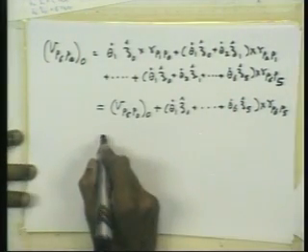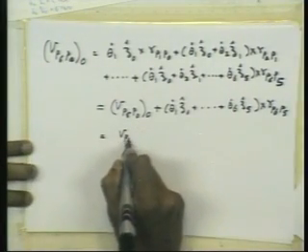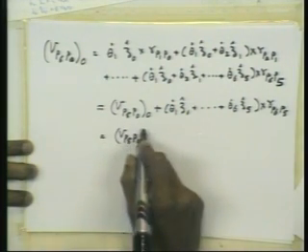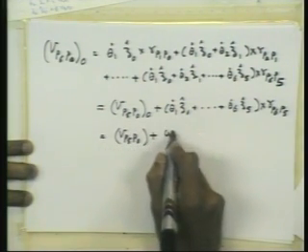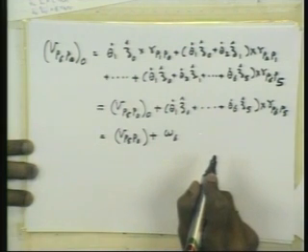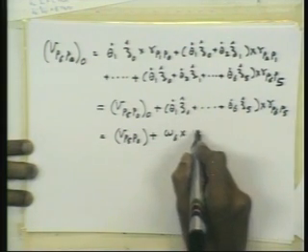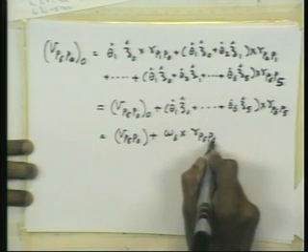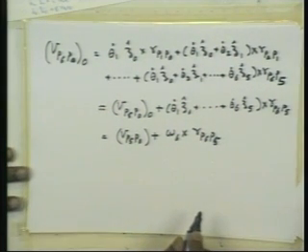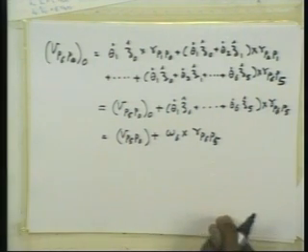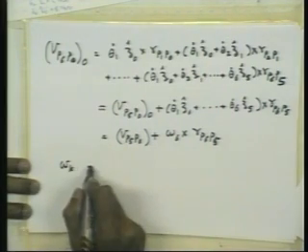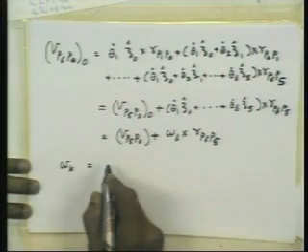So this is nothing but, basically, the velocity of the point P5 plus the angular velocity of the sixth link cross multiplying the vector from P5 to P6. So in this serial chain, the angular velocity of the kth link, this is a vector by the way, is obtained very easily.